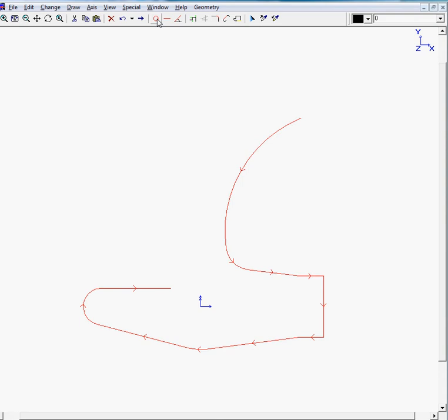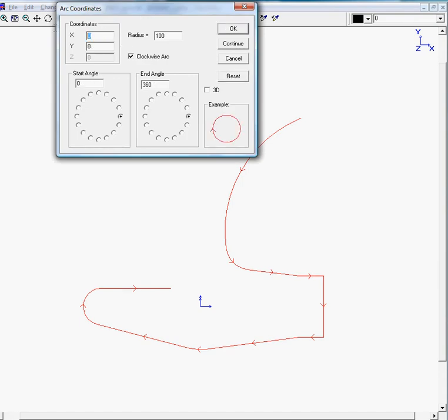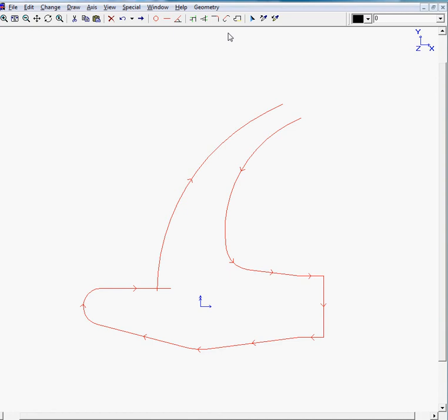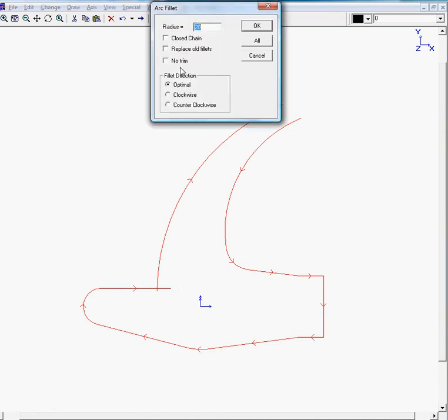So we move on to our coordinates, reset. The x value would be -80 plus 210 if you look at your drawing, because that's the way it's being dimensioned. The y value of this R165 is 12.8. My radius is 165. It's also clockwise from this point to almost this point. We click on OK, and we will define the fillet in this corner, which is 25.